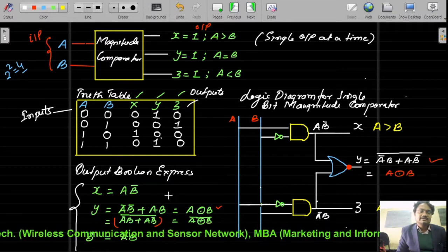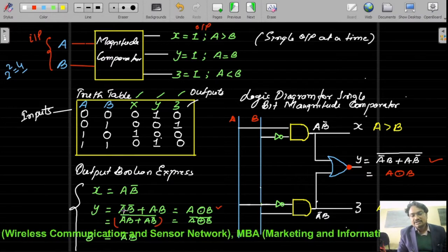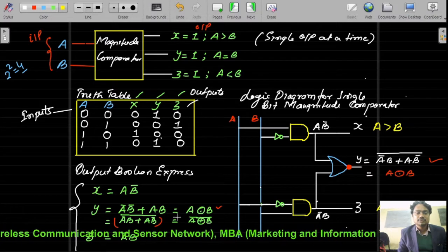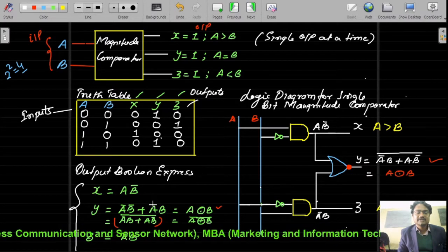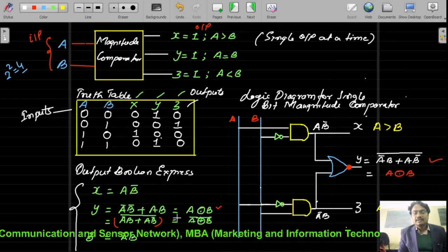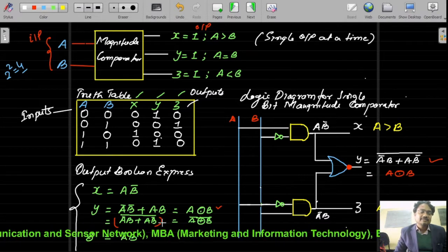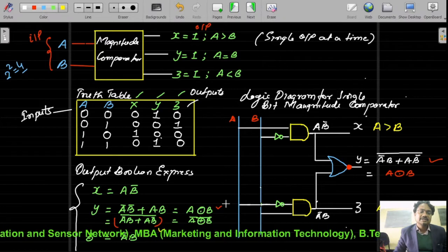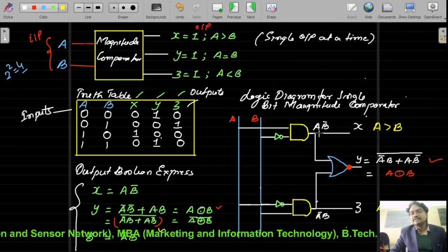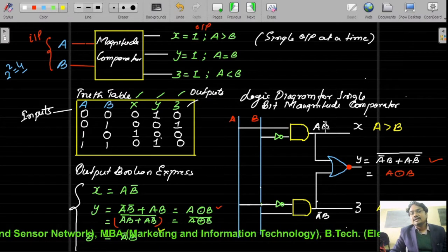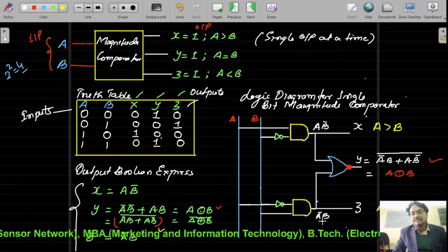And now finally you can see, just as we have told you, that this is a standard XNOR expression. This XNOR expression can be written as the complement of XOR, and we have taken advantage of this here in this fashion, because at this output we have a b bar, and here we have a bar b.